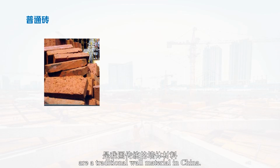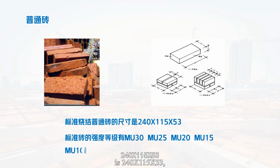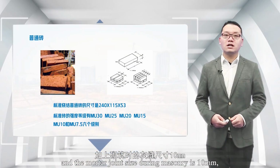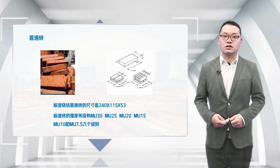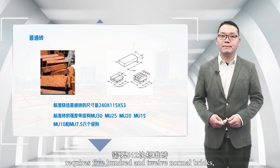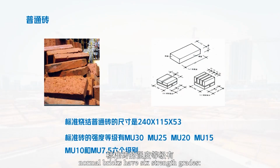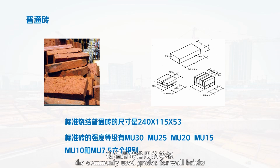Sintered common bricks are a traditional wall material in China. The standard size of sintered common bricks is 240x115x53, and the mortar joint size during masonry is 10 mm, forming a scale relationship of 4 to 2 to 1. Building 1 cubic meter of brickwork requires 512 normal bricks. Normal bricks have 6 strength grades: Mu30, Mu25, Mu20, Mu15, Mu10, Mu7.5. Among them, the commonly used grades for wall bricks are Mu10 and Mu7.5.